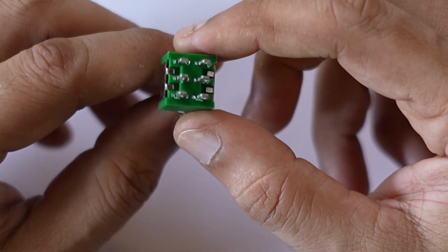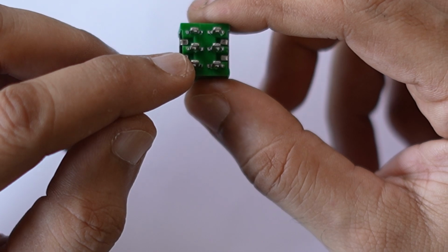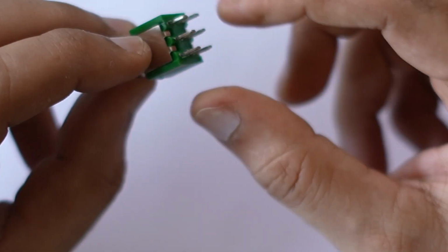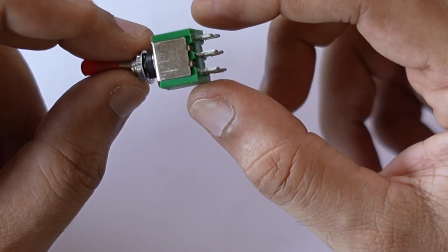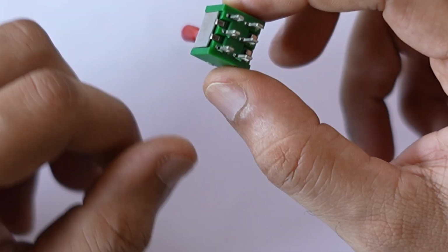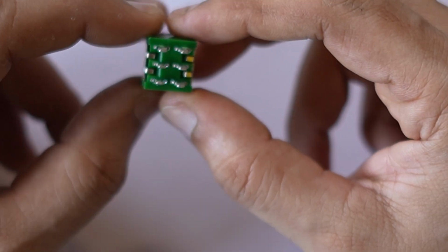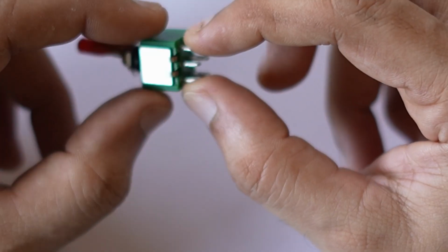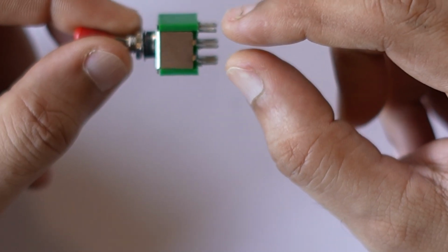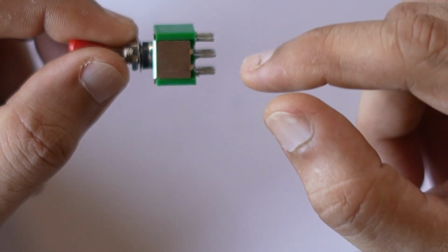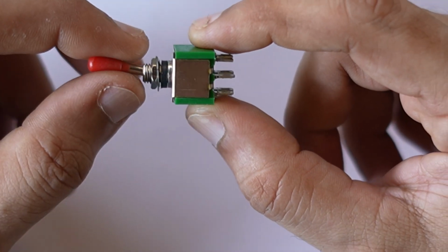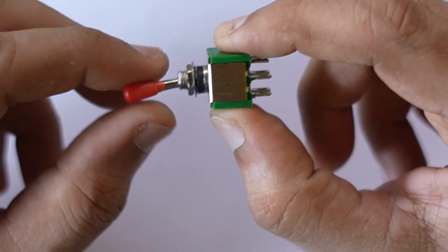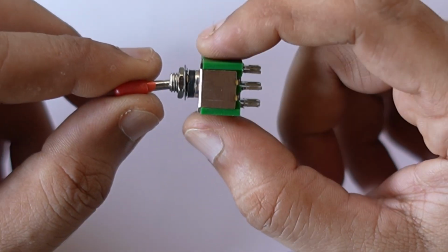You can have a single pole switch with double throw, meaning it will have 3 terminals, a center and top and bottom. That's a single pole switch. And the difference between double throw and single throw is in a single throw switch, you'll have just 2 pins, which is either on and off. In a double throw, you'll have contacts on both sides, and there's no off literally in that sense. You just turn it in the other direction, and the center and the top go off, for example.